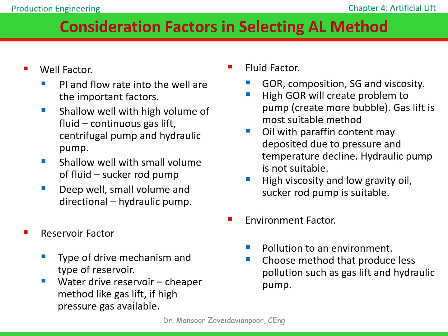So, whenever you're selecting an artificial lift system, think of it as balancing 4 questions. What can the well deliver? What does the reservoir look like? What fluid are we producing? What are the environmental and operational constraints? Only after answering these questions can we confidently choose the most appropriate lift method.